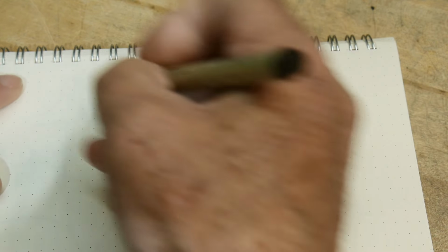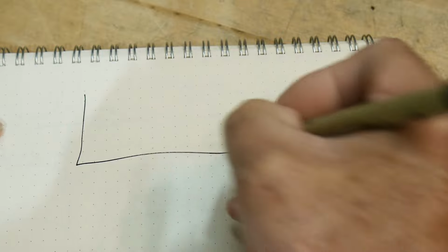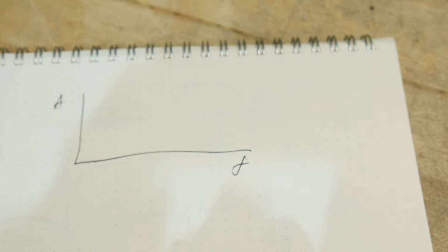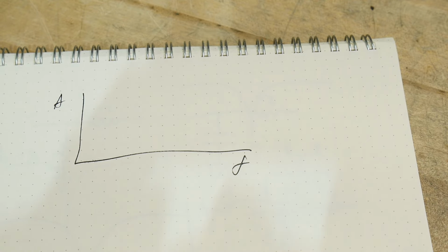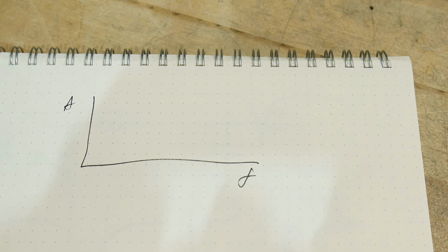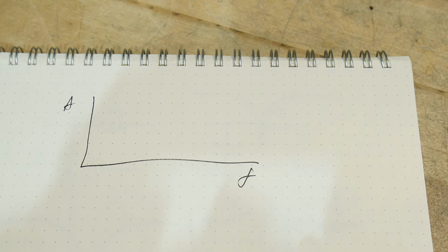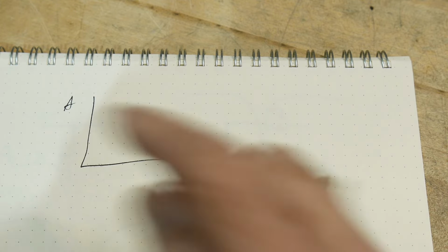That is, if we have a system where we have frequency and amplitude, and we're trying to, you can call it a bypassing capacitor, decoupling capacitor. You want to remove the noise in a system. That's why you add capacitors, is to reject some of that noise, and you want to basically shunt that noise to ground. And that's a lot like those pictures I just showed you.